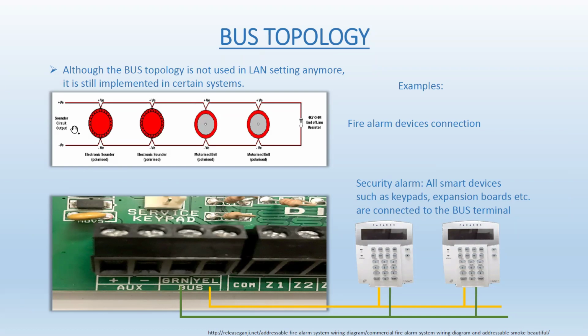So if you have a bunch of devices connected to the west hallway or something like that, and those are basically a bunch of smoke detectors connected to that one zone, if any one of those gets triggered, the panel would annunciate that smoke detected west hallway. Just kind of pulling that out of the air, the names, right?